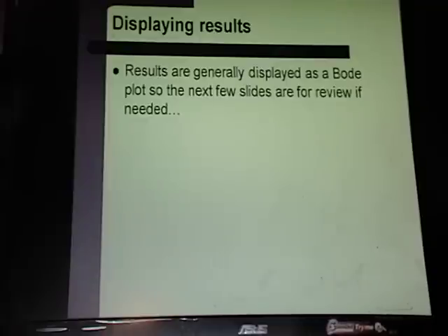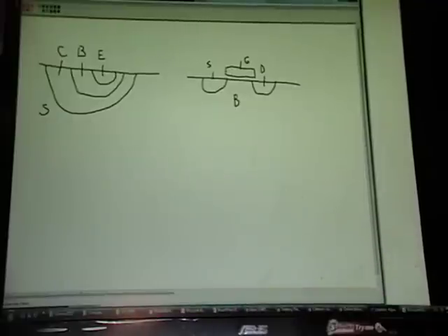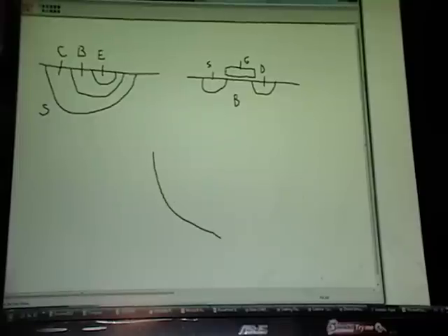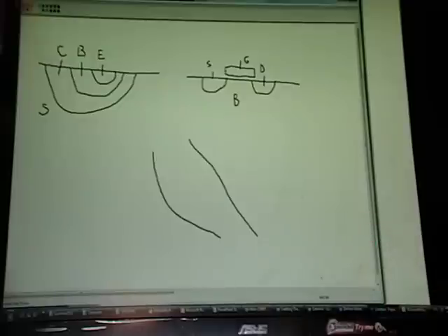It's hard for a human to look at a line and say, yes, that's an exponential. It's hard for you to say, oh, yeah, that looks like an exponential, but is it really? You don't know. But if you put it on a log plot, now it's a line. And humans understand lines. We can detect whether something's a line or not. You just can't really tell if this fits e to the minus t over RC.